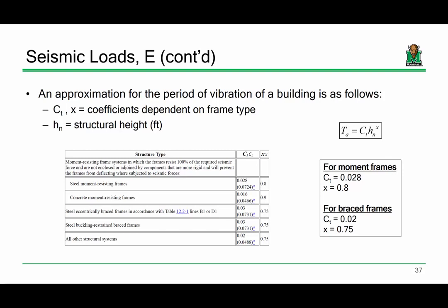Usually what you're trying to do when you're changing the damping characteristics of a structure is you're trying to install elements to do that. So tuned mass dampers, there are base isolation techniques where you sort of sit the building on some elastomeric rubber pads that change how the accelerations get distributed to the building. There's a couple of different ways to do it. There's a boatload of different ways to do it. But that's, man, I could talk about that all day.